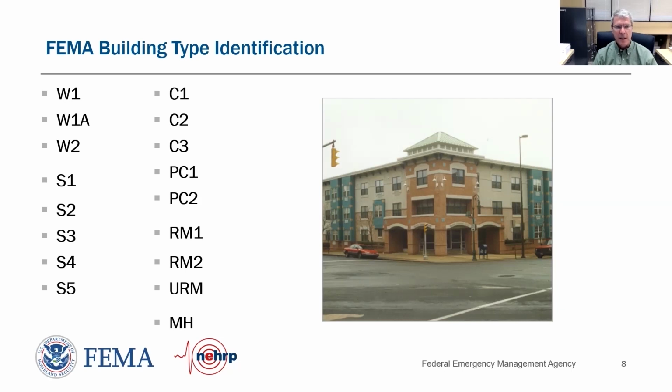And then you want to still keep wood in. Well, it's not a single family home, so it's not W1. You know, it looks like almost like one of those buildings where you have several stories of wood over a concrete garage, but I don't actually see any distinguishing concrete podium here.